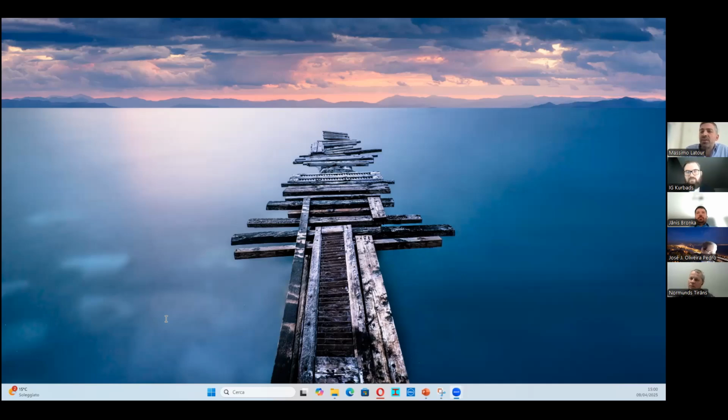And if I remember well, there is a third, more simplified approach, which is simply taking the design action magnified with an overstrength. I don't remember exactly what number is given, but it is very simple because we just perform the analysis and magnify the action by a factor, which I think is very used in practice as well. But the idea is to have an overstrength also in the foundation, for sure.